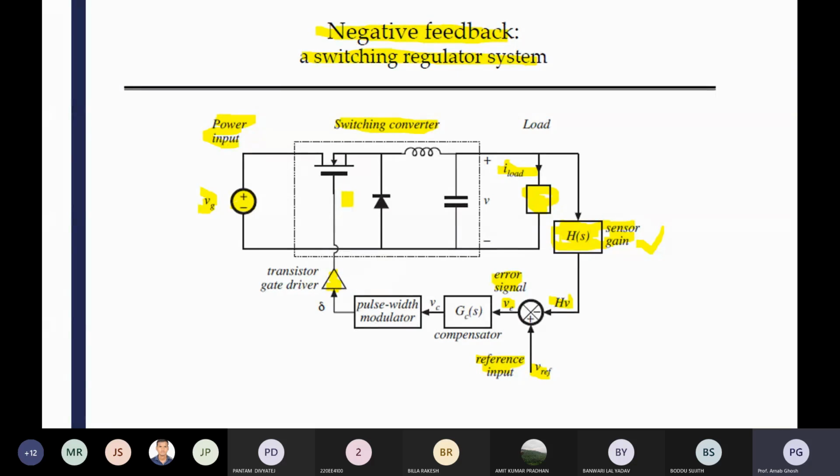For a costly device it is mandatory, but if you are doing a small circuit for your own laboratory testing purpose, in that case you may not use that isolation. Basically, that sensor cost is too high. The LEM sensor, LV25V, costs about 3000 to 6000 rupees. So you use it only for sophisticated applications, like a control board that costs maybe more than a lakh. In that case you have to use that type of isolation.